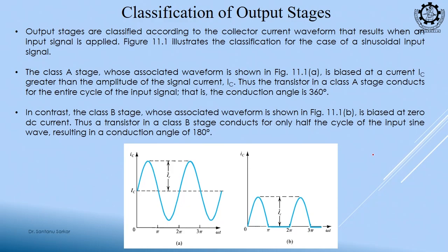Suppose you have a MOSFET or you have a BJT and for all conditions you want it to be on, this signal will be connected here, right. Along with this signal you will also have the DC biasing superimposed. You want to ensure that there is a certain DC value, and on top of that DC value you are having the AC signal.